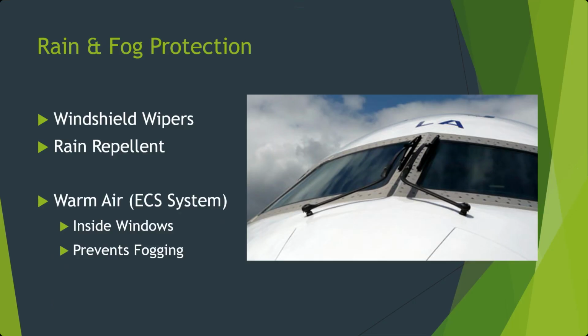They are relying primarily on instruments for keeping the aircraft on track and flying straight and level, and then also things like TCAS, Traffic Collision Avoidance System, to be on the lookout for other aircraft, and weather radar for that, and then air traffic control. At the altitudes and speeds, and particularly in low visibility conditions like night, the view outside really is a small part of the situational awareness.